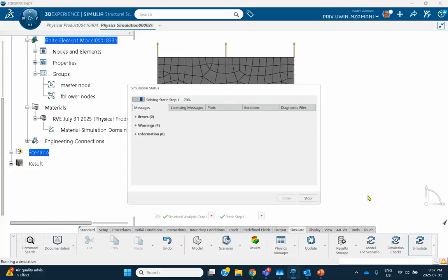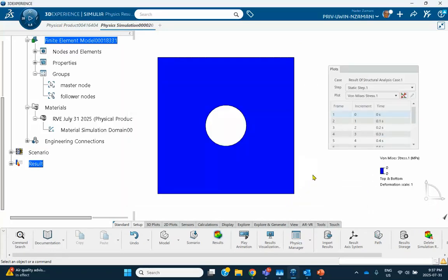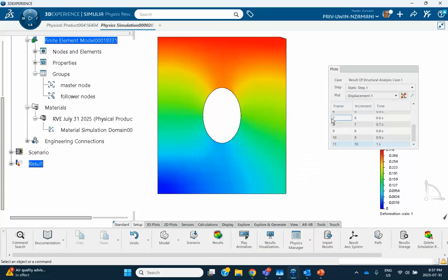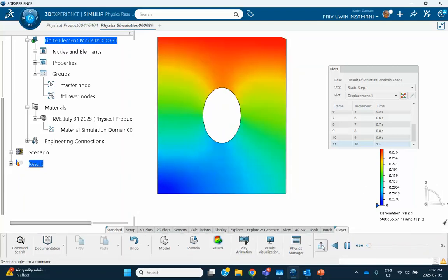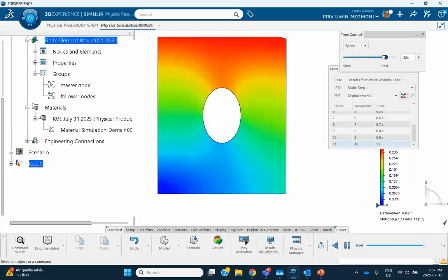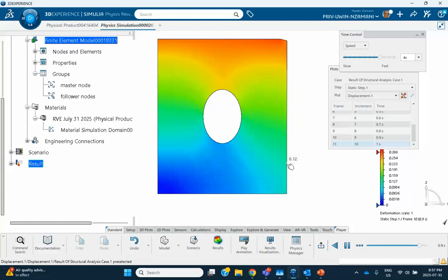This is doing a nonlinear calculation because of the fact that strain is large. Extracting results. All right. Okay, very good. So let me close that. I don't want the first increment. Let's check the displacement first. Displacement, okay. So notice that we can animate it actually. Animate. We reduce the speed here. See that line remains a straight line. And I'll show you what happens if I take that coupling away.